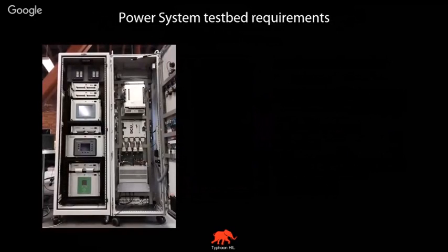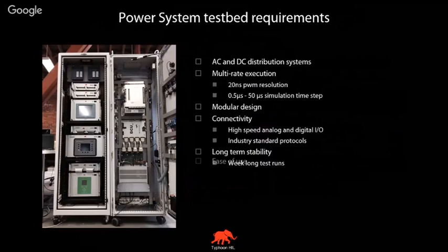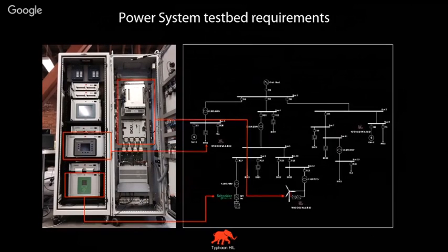Now we are expanding to the microgrid level and power system levels by adding some slower dynamics on top of this. If we speak about the power system testing requirements to perform something like this, then we speak about a combination of different simulation platforms that are executing different parts of this model on different time steps. For example, for most of the power system simulation, we are completely happy with simulation time steps of 10 microseconds or maybe 20 microseconds, depending on the level of detail we need.